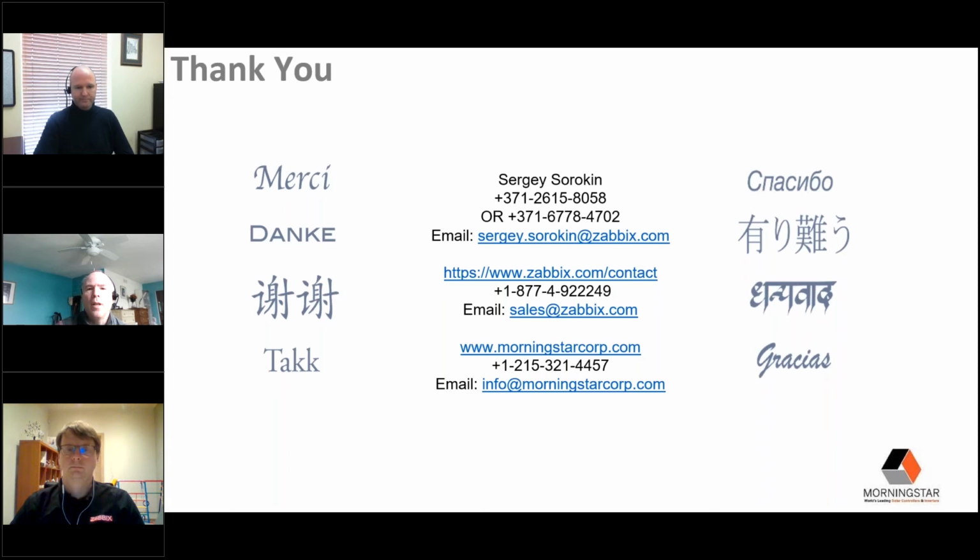Okay, well put. A couple of questions here about, do you need an EMC1 for each Morningstar product that you're monitoring? Yes, at this time right now, it is a one-to-one relationship. It uses a serial link, so it's a serial RS-232 connection between the product that we're actually controlling and the EMC gateway, and it takes that interconnection and then provides an IP address on the WAN side of the network so that you can communicate it anywhere in the world.